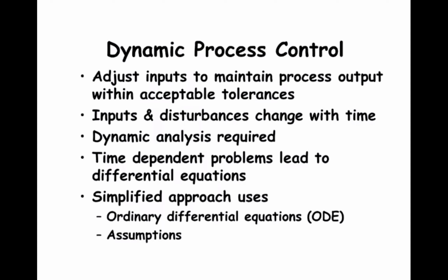External disturbances are uncontrolled. For process control, we need to adopt a dynamic analysis to assess the process response. The process response will depend on the process, the sensor, feedback elements, control mode used, and the actuator used. We will talk about process response later in the course, but it is one of the reasons for all of the mathematics and approaches happening at the beginning of the course.